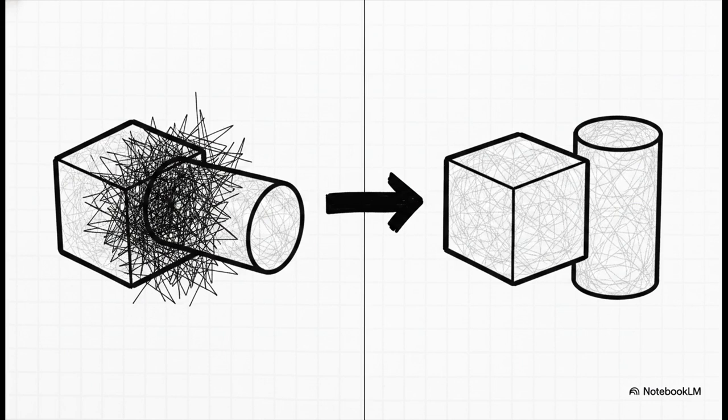This is absolutely crucial. Imagine you have 2 parts fighting for the exact same physical space in your file. If you don't detect and fix these overlapping solid parts, they will completely crash your simulation setup and cause your meshing algorithms to just fail outright. The software literally cannot calculate the physics if the geometry is physically impossible.